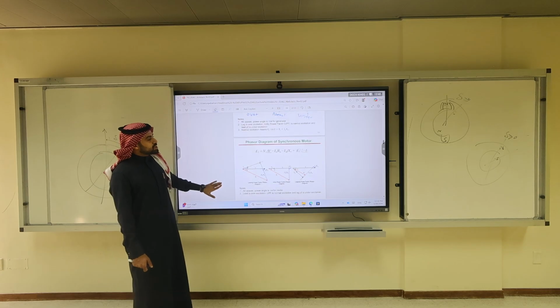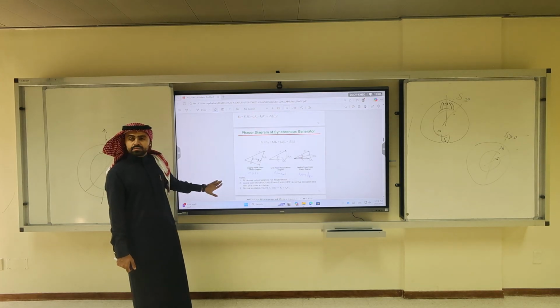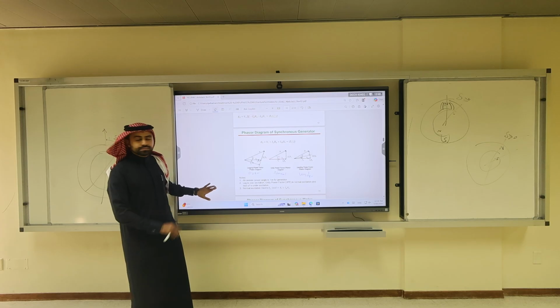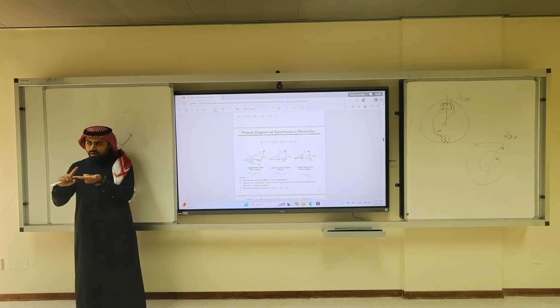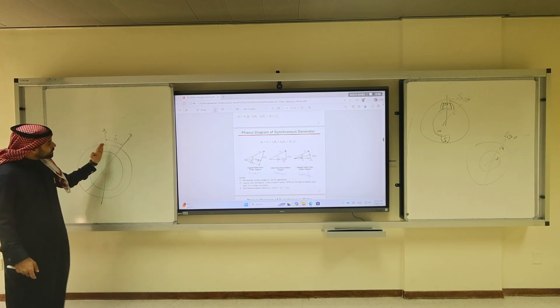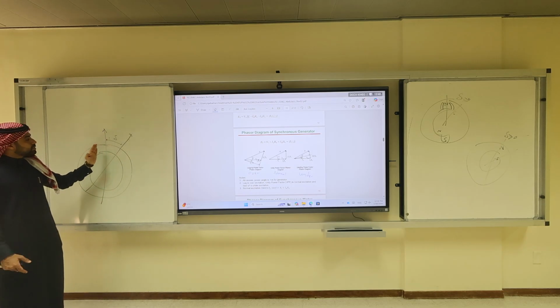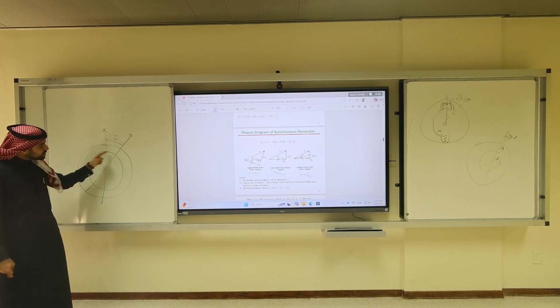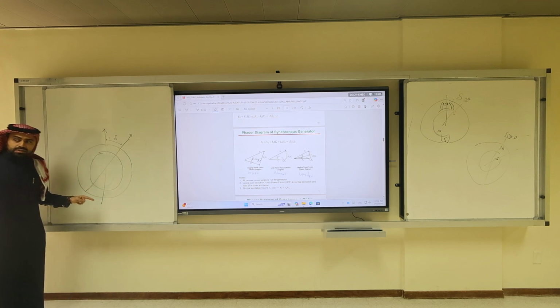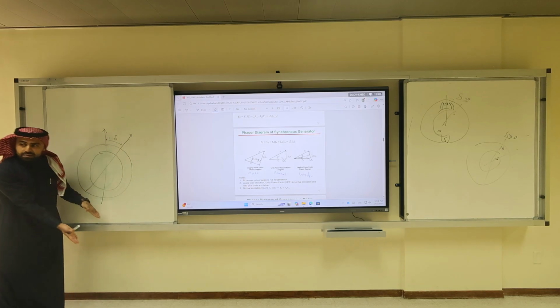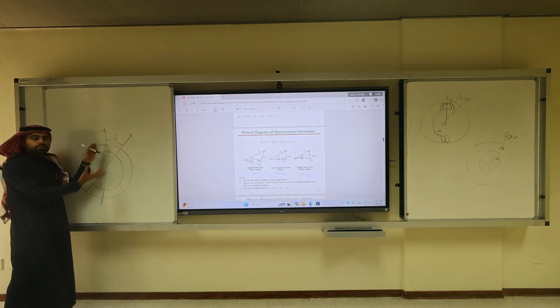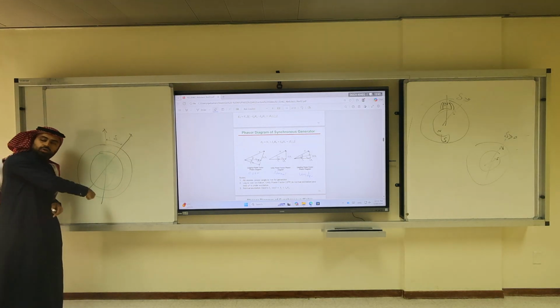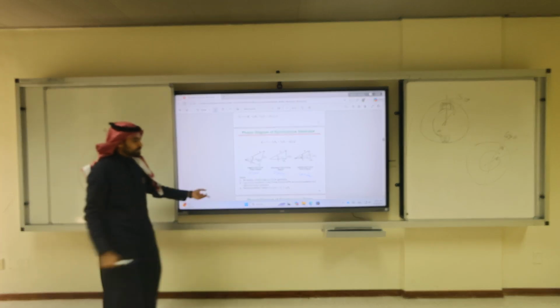Now, any question about the phasor diagrams? I think they are clear, correct? Are they clear? Yes. So again, what is delta? Power angle, also known as the torque angle. And it has to do with the deviation of the flux lines, the peak of the flux lines between the rotor and the stator. Keep in mind, if this spins at 60 hertz, the whole thing would spin. It's not that delta will change over time. Delta will change if you demand more power. If you add more torque to your machine, delta then will change.